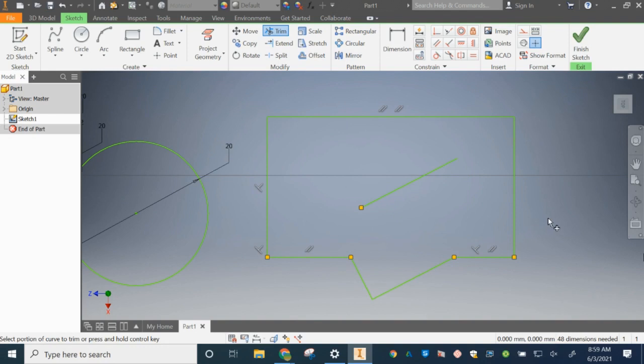And the opposite of that is the extend tool. So I'm going to be extending the lines out. It's going to extend until it hits another line, which is helpful. This is a very helpful tool when you're making a shape and you're trying to extrude it and there's a hole in it. So there we go. Now I have that line actually touching, so it's a completed shape.